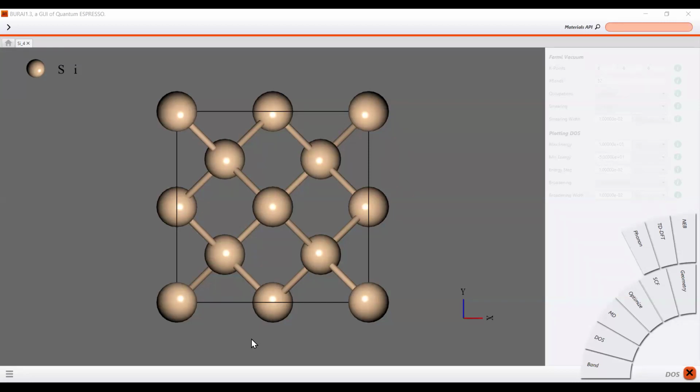So for optimization of the U parameter, we have to do it manually and optimize it, right? We give one value, do the calculation, then give another value, and like that we have to do, right? This is a very conventional method. Also, you can go to what I will show you. In Quantum Espresso there is hp.x. You can use the hp.x executable for finding the Hubbard parameters.